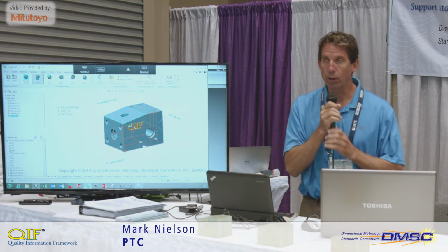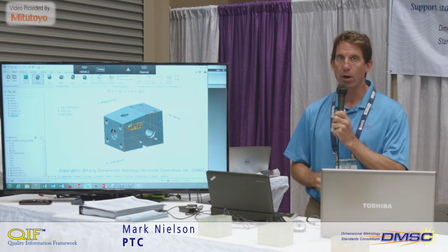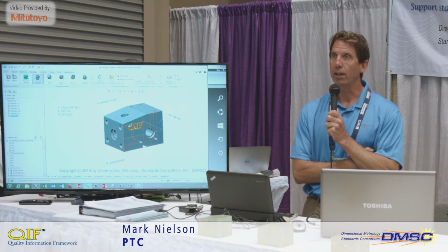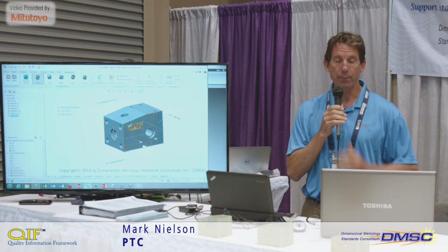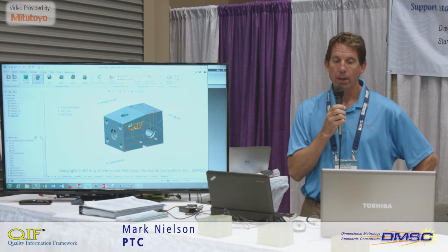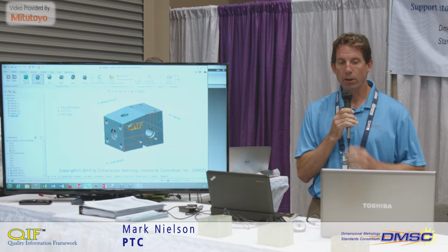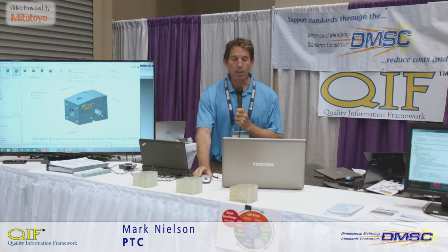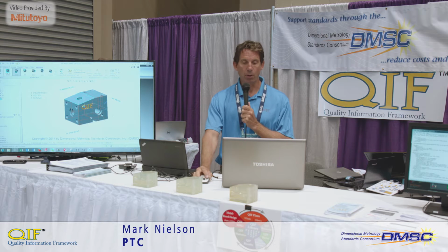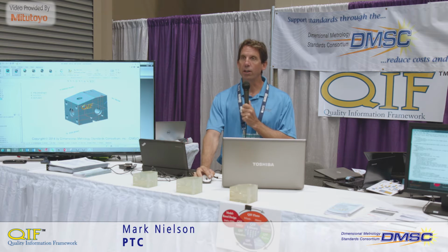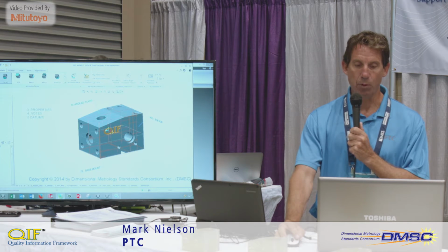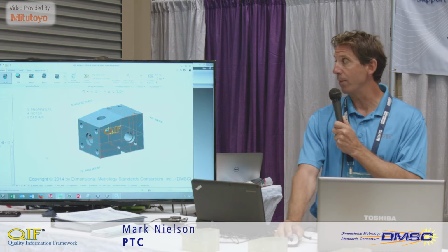We're going to go through the CAD model here that we created using annotation features and elements for designing the model. This model was created to the MIL standard 31000 schema, where we have certain combinations of items at the bottom here. You'll see these various tabs that are set up that show different layouts of the model. This is for the typical model-based definition. Here you see what we call the site map.